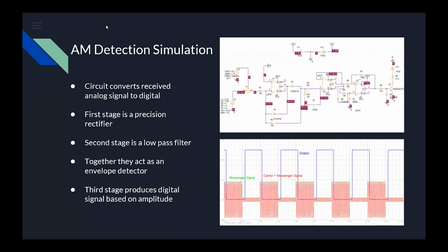I understand. But what I'm saying is, what was the information that was retransmitted by the transponder? The transponder sends only its 4-character identification key. Ranging is done entirely on the interrogator side using round-trip flight time measurement.